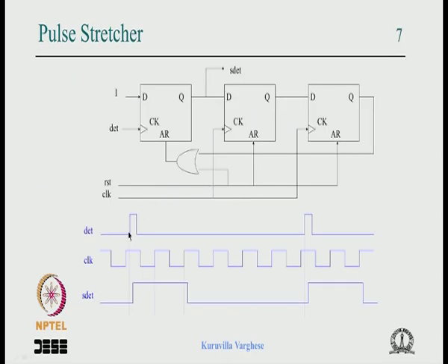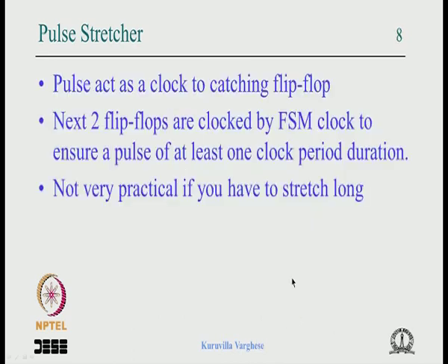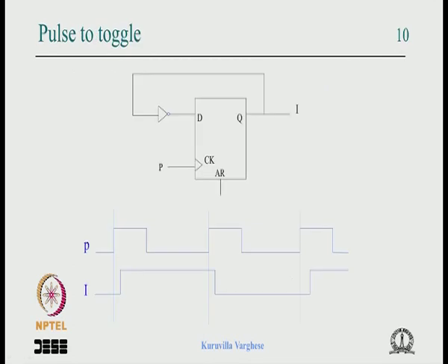What we do is, as output, when a pulse comes, the output goes high and stays there till the next pulse comes. When the next pulse comes, it goes low and goes to the state machine, and what the state machine does is that every edge, every positive and negative edge, you can make a pulse, and that is a pulse to level converter.